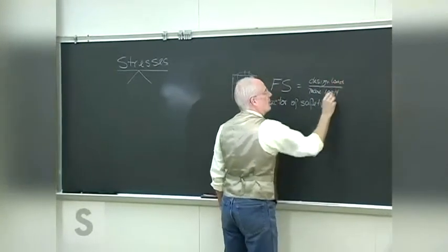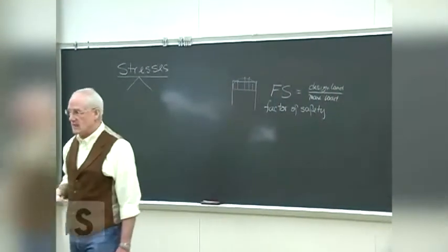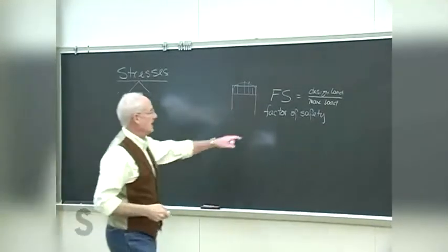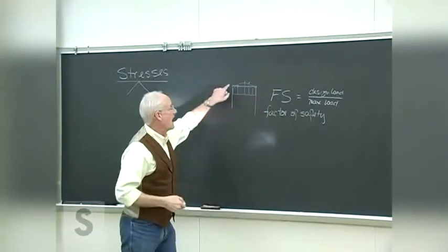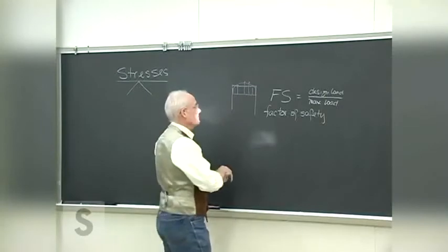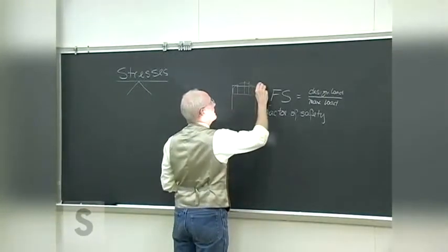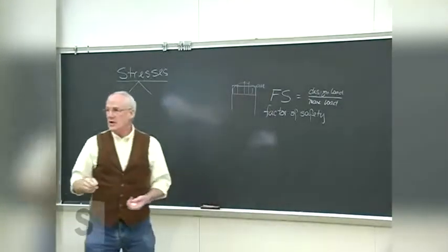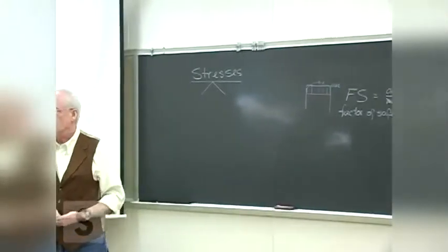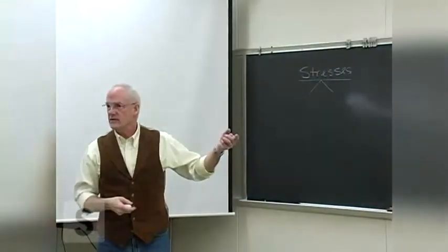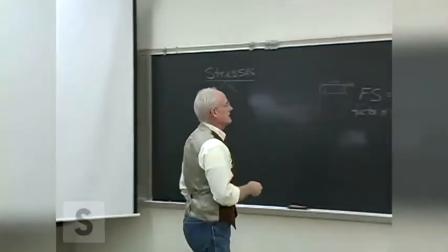In other words, once you've calculated what the maximum loads are, and again, we may take this as an average value, which means we're a little bit worried that we're underestimating the stress at certain places. We apply this factor of safety, which takes us way over the top.